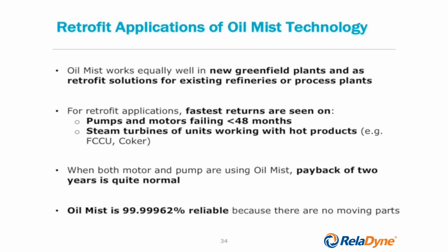And then, generally speaking, the operator can almost immediately refill, for instance, the oil reservoir, and there will be no failures of the pump, because the pump or electric motor, in the 8 hours that it has run without that external oil supply, will still have a sufficient amount of oil clinging to the rolling elements of the bearings, and as a result is adequately separating the rolling parts of the bearing from the non-rolling parts.